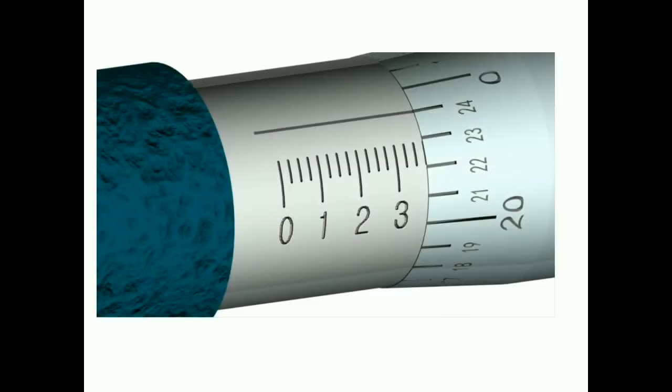Okay, so here I've taken the micrometer and I have moved it just a little bit back, so we're just a little bit less than 0.375, and the question is, what's the reading now? Well, we're not reading from this mark anymore. This mark is not actually showing, even though you can kind of see it. If this mark were to show, it would be a brand new mark, and so the reading on the thimble scale would be a very small reading, and as you can see, we're reading 24, which is almost completely all the way around. So this is a very high number, so that means we're working off of the older mark, which would be this one.